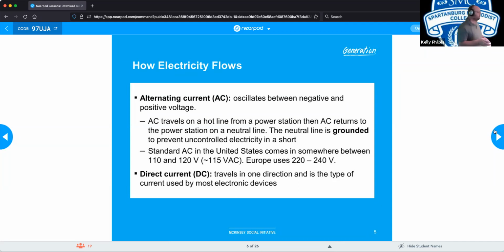Thankfully, most modern power supplies today auto select between the two. So it may be set automatically for 110. If it receives more juice, it'll automatically kick over to 220 and save the unit and still be able to function. You will not know this is happening. It just is done internally. So the selector switch is kind of going by the wayside for an automatic selection. Questions so far?